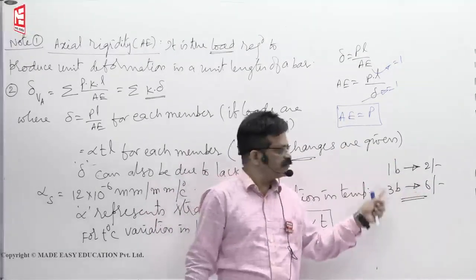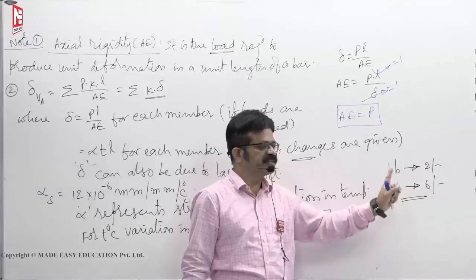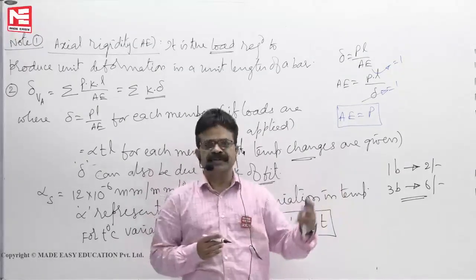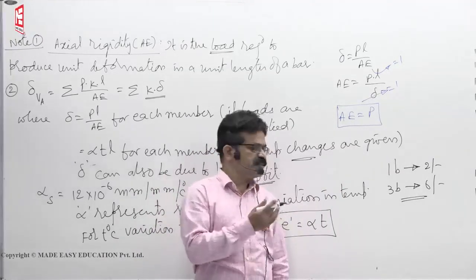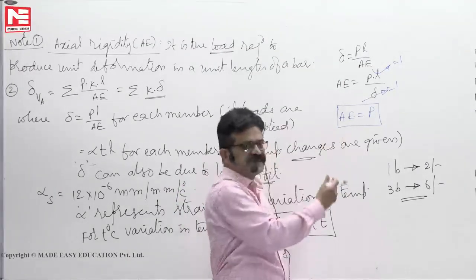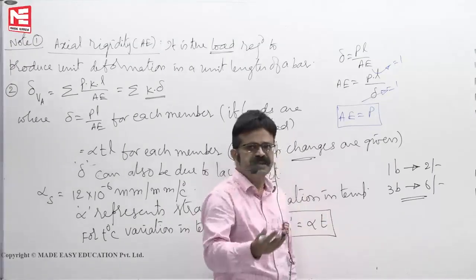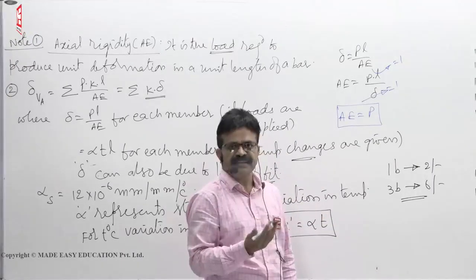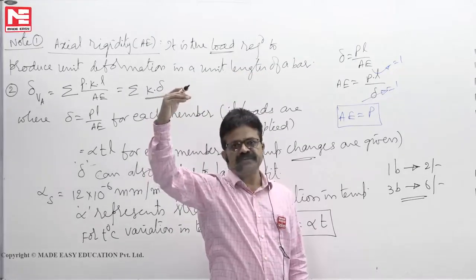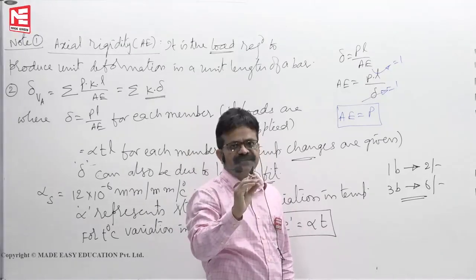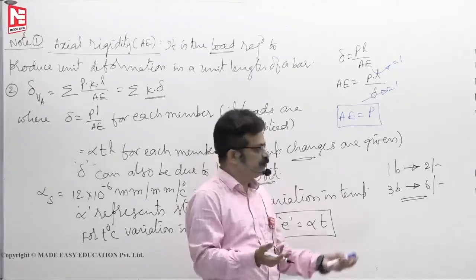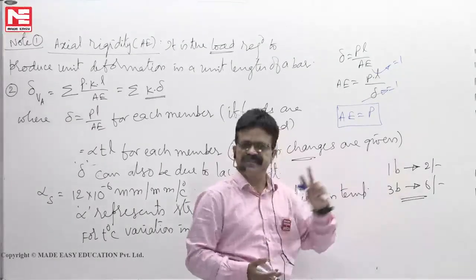If we know this simple logic, 50% of strength of materials is over, everywhere same thing only. Temperature stresses or fixed beams, wherever you take it, if 1 deflection produces so much stress, 10 deflection will produce how much stress. Like that bending stresses also: neutral axis 0, at a distance of 200 if 100 Newton per square mm is the stress, at a distance of 20 from neutral axis, what is the stress? Again linear interpolation. So most of the places you have used only this much.